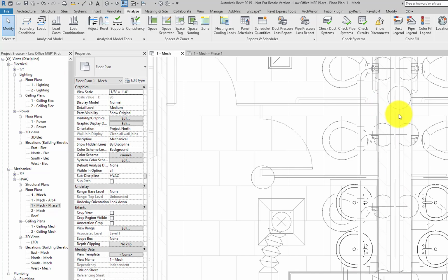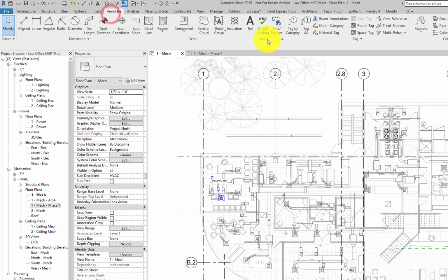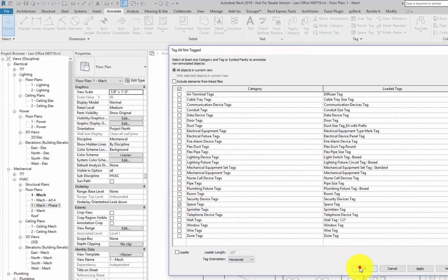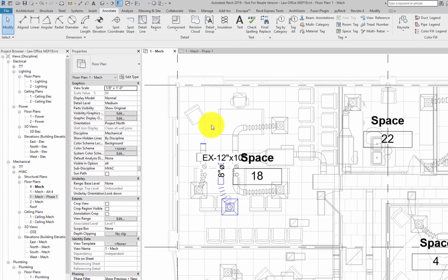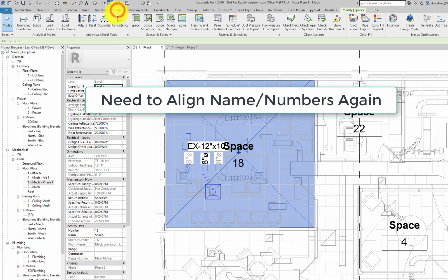That makes things go much smoother if you're doing energy modeling or lighting analysis with something like Lighting Analyst's Illuminate tools add-in for Revit. When you do the place spaces automatically, which was just done, it places spaces in every enclosed area, including the plumbing walls, like we saw, the enclosed space behind wall-mounted toilet fixtures.